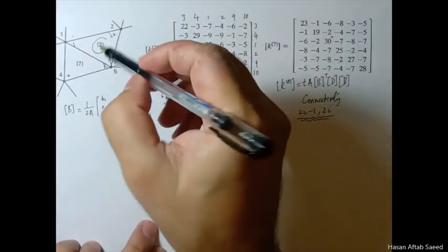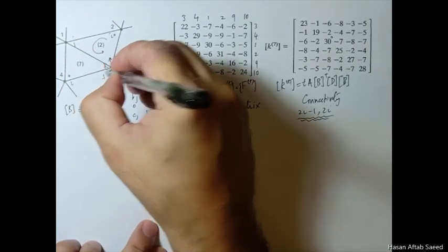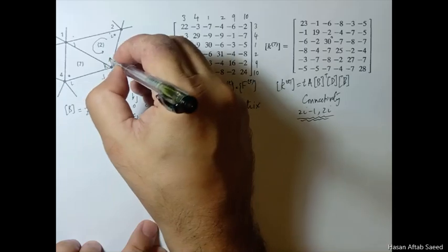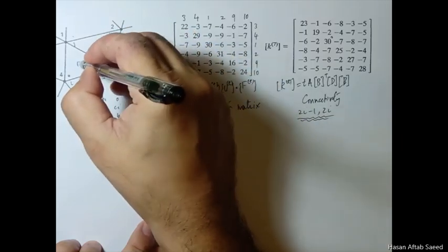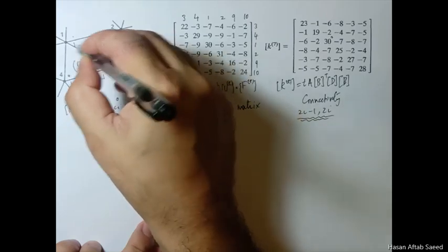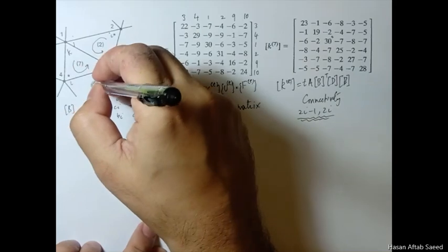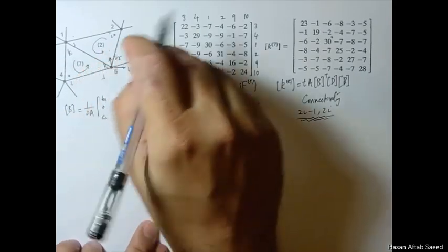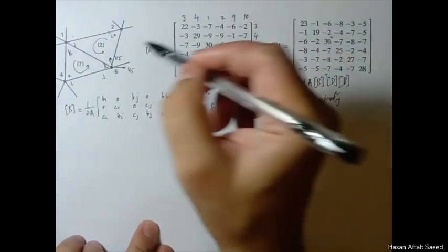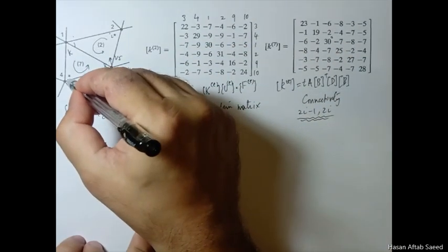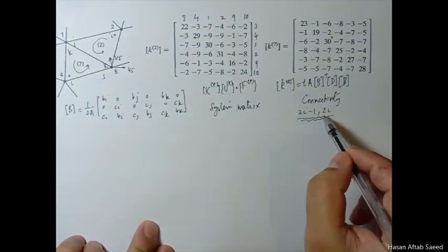Similarly for K7, this is the I node and this is the J node. Now this 5 node was the K node for this element, but the J node for this one. There's no difficulty here, because each element is different. It's I, J, K. So if you talk about the connectivity, the mapping from the node number to the degree of freedom, then for the I node, again use the same scheme, 2 into 4, 8 minus 1, 7 and 8.